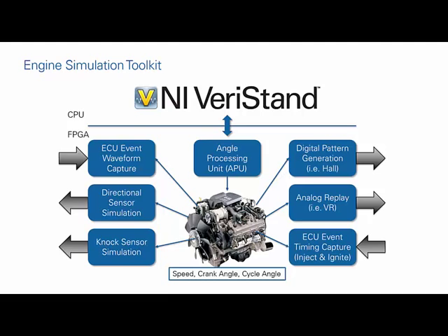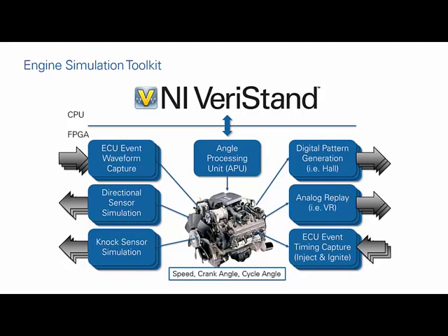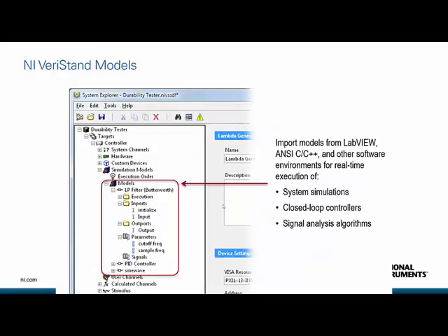Pattern generation, replay, angular processing, so we're able to measure or simulate where the engine is in its rotation. So all sorts of different real-world requirements for doing engine simulation. And then we can essentially simulate as many engines as we want because of the scalable architecture of this toolkit. Again, this is available for anybody doing engine control HIL. This is a really useful toolkit, and I strongly recommend it. This is a great example of the community and the add-ons that are available for VeriStand.